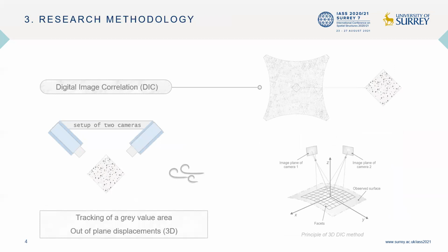Digital image correlation is a full-field image analysis method applied on gray value digital images to determine the contour and displacements of an object under load in 3 dimensions. A stereoscopic camera setup is used around the model to achieve a 3-dimensional interpretation. This research enabled us to obtain a method in which precise membrane movements are detected.